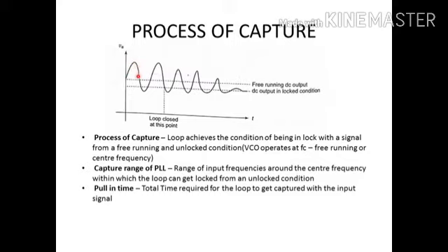Sometimes it is high and sometimes it is getting low, and again it is getting high and again it is getting low. So finally, in one particular case, you can see that the error voltage becomes equal to 0. Only when the error voltage becomes equal to 0 is the PLL said to be in locked condition. When the error voltage is 0, the VCO output is not allowed to change. So it means that the PLL has entered into the lock condition.